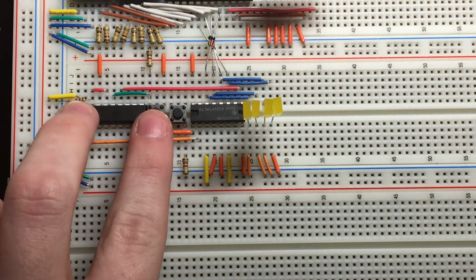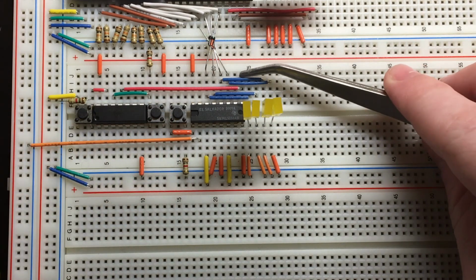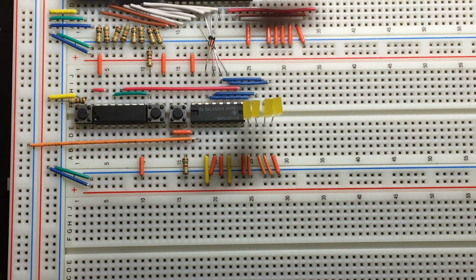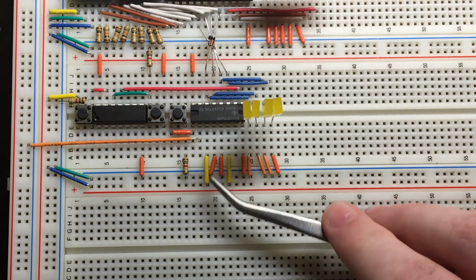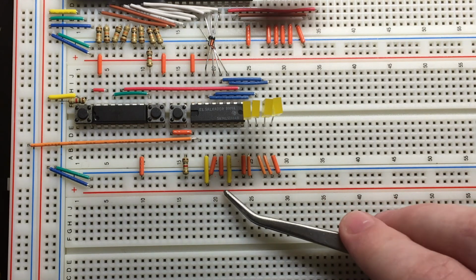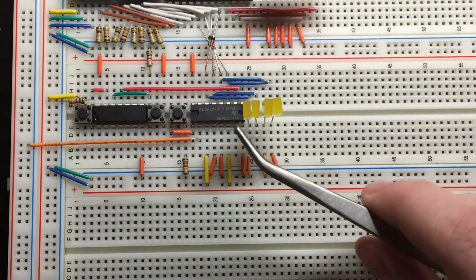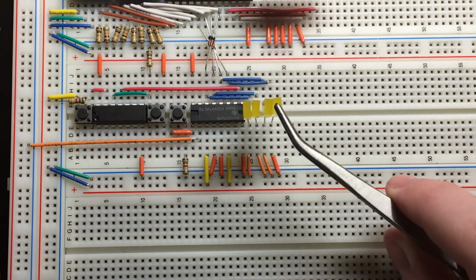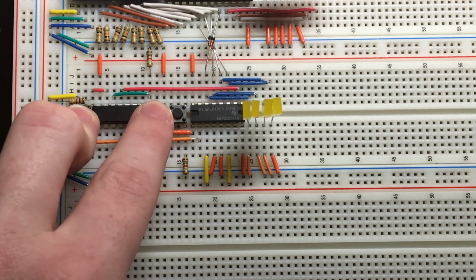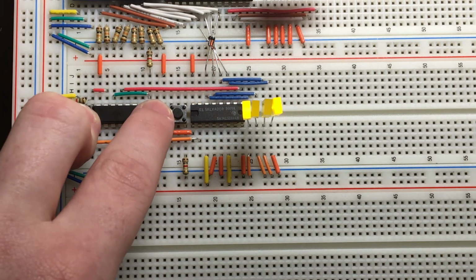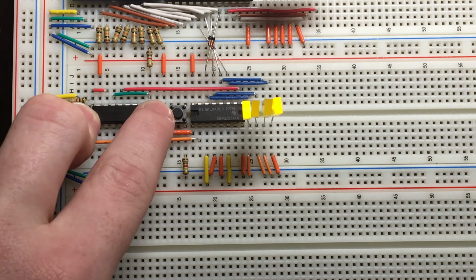And then this button is a load button. So there's a load pin. It's the final pin right here. And that basically sets the inputs, which are these. So this is 1, 0, 0, 1, or high, low, low, high. So when I press these 2 buttons, this LED and this LED should turn on with a clock input. So if I held down these 2 buttons and use our monostable clock, you will see that it'll be on, off, off, on. So that's the load pin.